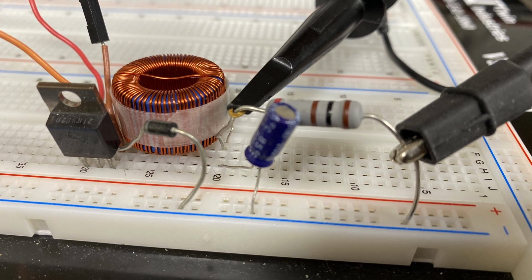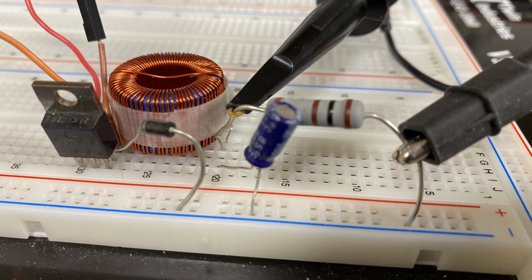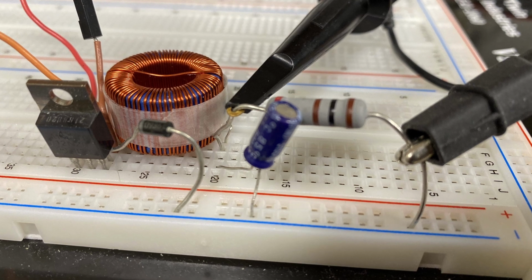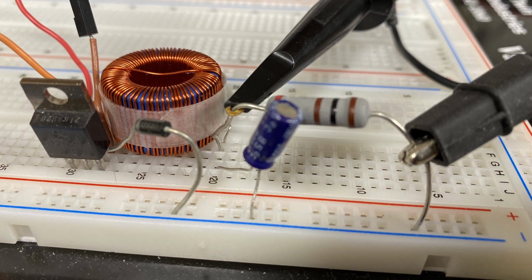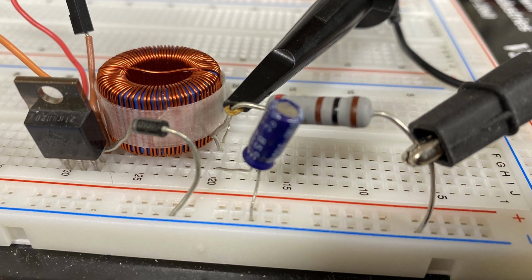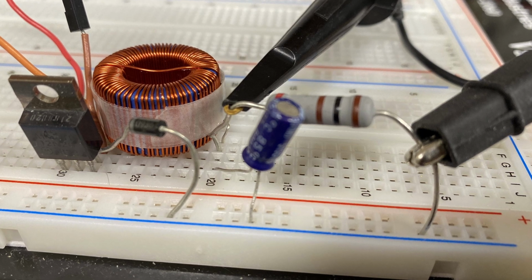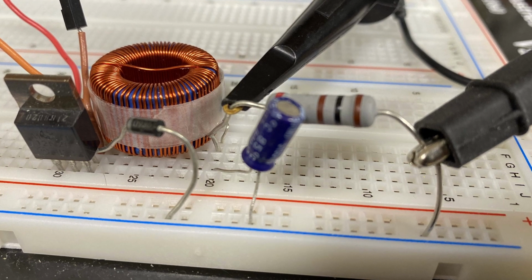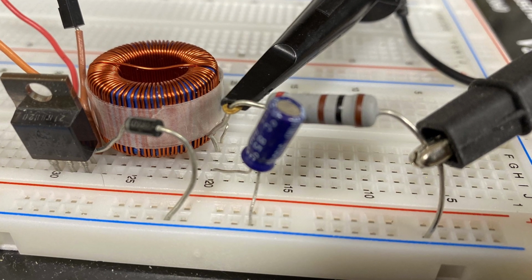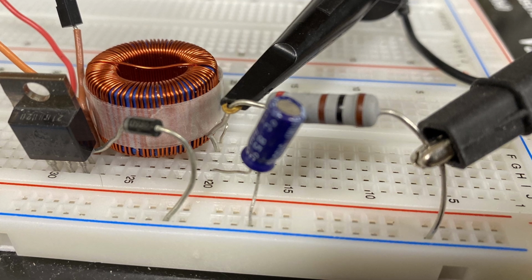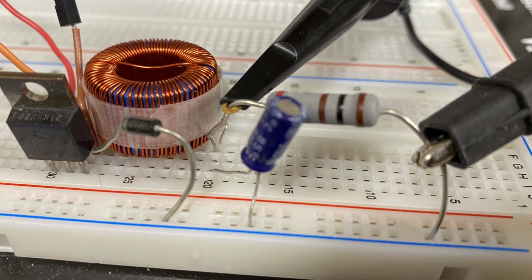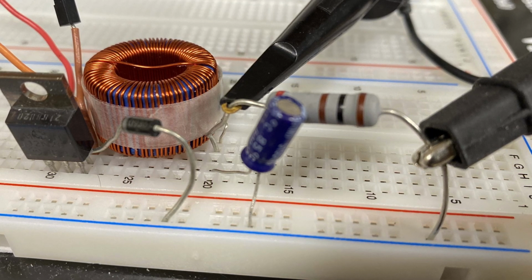The output voltage of a buck converter is less than or equal to the input voltage, and the required value for an application can be obtained by changing the duty cycle. Say to get 6 volts from a fixed 12 volt power supply, we can use this converter to supply power to the load. In this video, we'll discuss the components needed for building one, test and validate the theory.